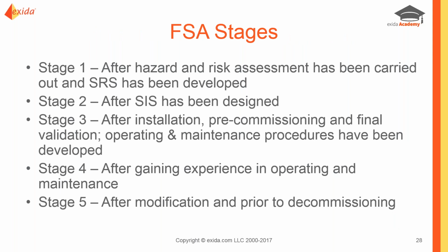Here are the 5 stages in which the FSA is required. The first 3, stage 1, 2, and 3, are through the design and implementation process. Stage 3 needs to be completed before we actually introduce hazards into the process. Stage 4 we want to do after we've gained some experience in operating and maintenance, and there's some track record there. And then of course stage 5 would be after any kind of modification or prior to decommissioning.